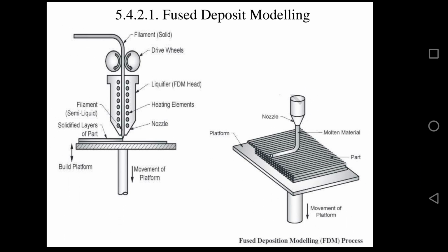So what are the parts or components we use here? We use a pre-processing computer. Every rapid prototyping process needs the pre-processing computer. Then we need the fused deposit modeling system computer, then the control unit. These three are used in all of them. We add extra things like the FDM head with dual tip nozzle, a platform heating system, and also a build platform to build the object.